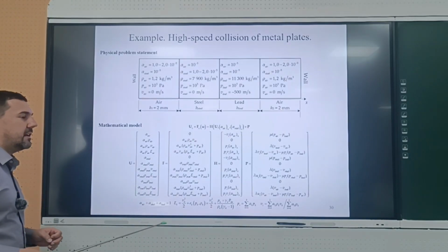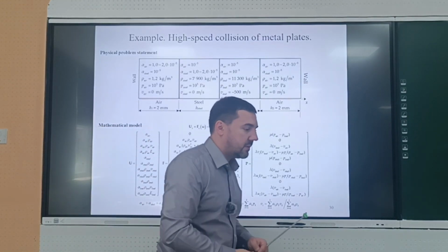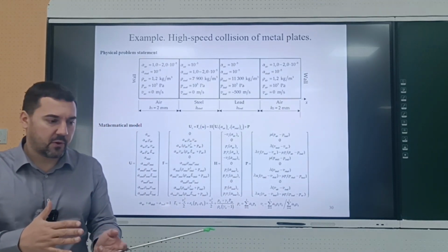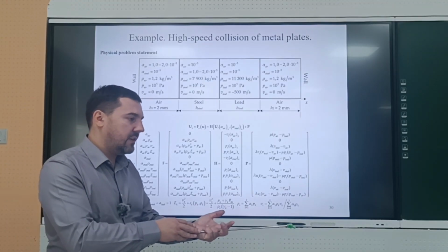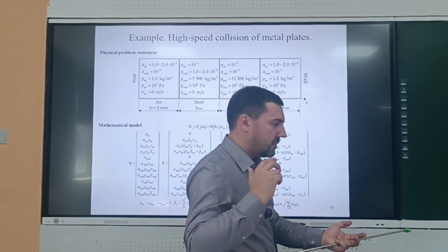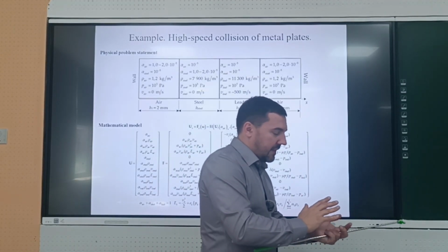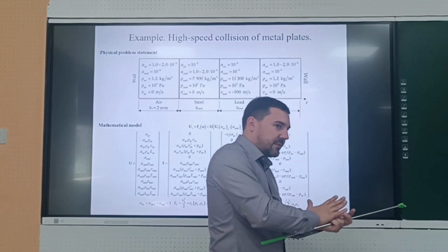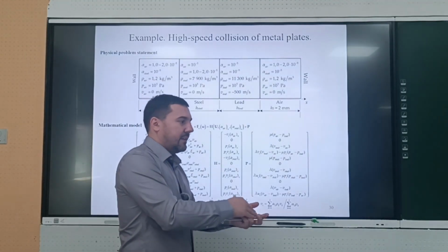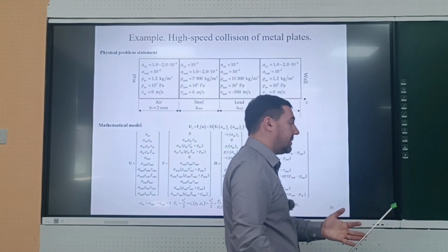There is a process called explosive welding. For example, in HIT we have the State Key Laboratory of Explosive Welding. It's a way to get materials with different properties. For example, if you have a plate of one metal and it is stationary, and you have a plate from another metal and it is impacted with a huge velocity because it is thrown using an explosive charge under some angle, and so they interact, and there is sort of mixing at the surface between the plates, and you get a specimen with specified properties. For example, the lower part has one set of properties and the upper part has another because they're from different metals. This process is called explosive welding.